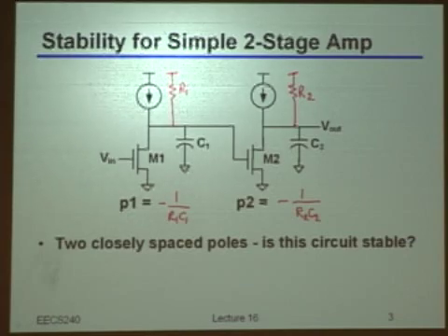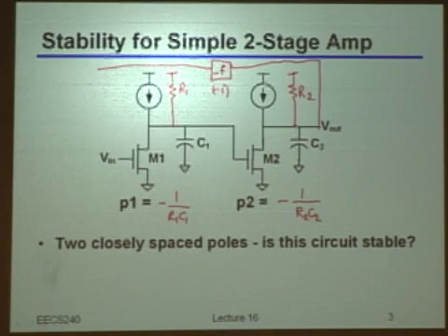So I don't know actually what's going on here. But okay, let's then be more precise. Let's assume that I have even unity gain feedback, like minus 1. Most of the time, when you consider only passive networks, unity gain feedback is considered to be the most pessimistic situation. But you might have some gain also in the feedback, and so that is even worse.